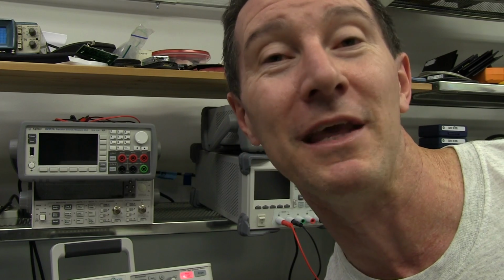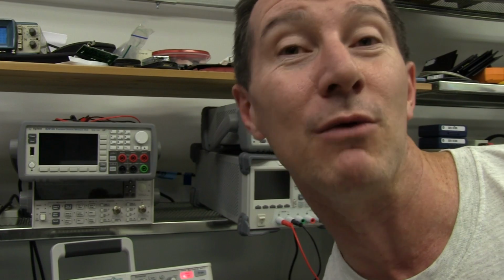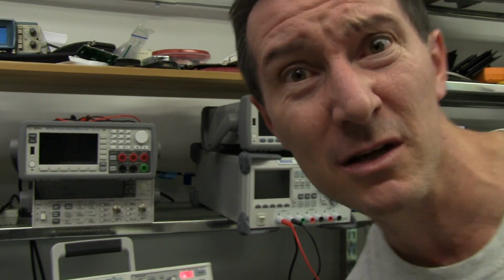In fact, the capacitance can go up, not decrease as we've seen, with an applied AC voltage, depending on the level, depending on the construction technology and the dielectric used in a particular type of capacitor. And it can even change fairly drastically between the same family with different size capacitors. Unbelievable. So the same family, the same type, the same X7R rating, or whatever it is, it can change. Man, I hate capacitors.